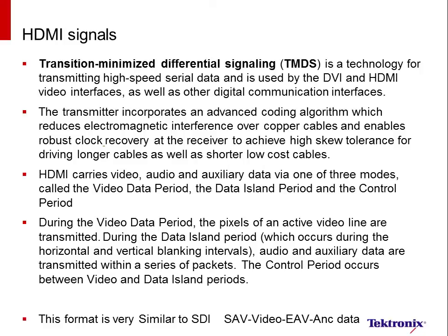This transmission format, from an overall look, is very similar to what we do in SDI, where we have EAV, SAV, and ancillary data in both the horizontal and/or vertical intervals. But as we'll find out in a few slides, there's quite a bit of difference after that point.